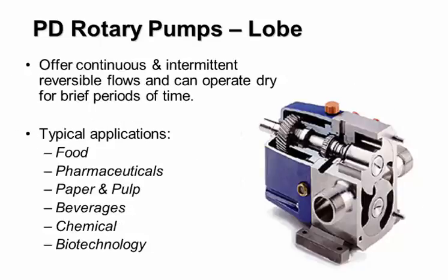And here's that example I was telling you about. Here's my input shaft. Attached to that is a gear. And what you can't see is another gear inside the casing here that's driving this lobe here. So these lobes do not contact each other. They do not contact each other, which means there's no friction between these two lobes.